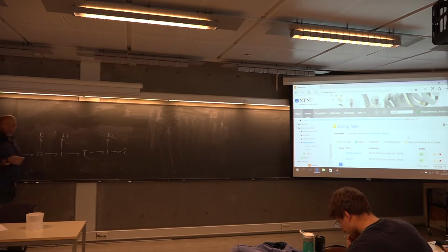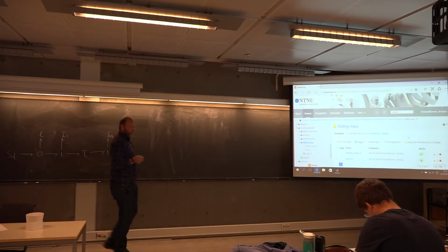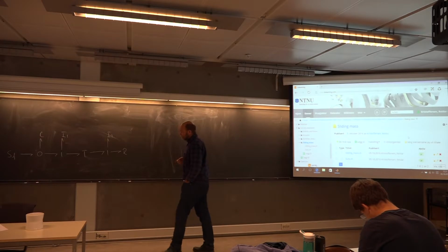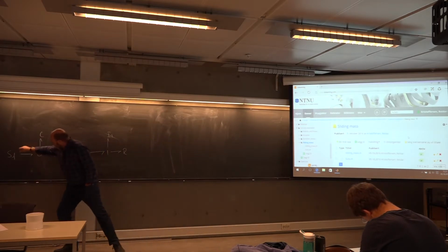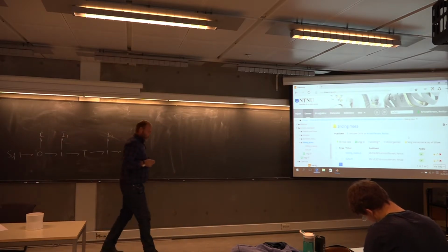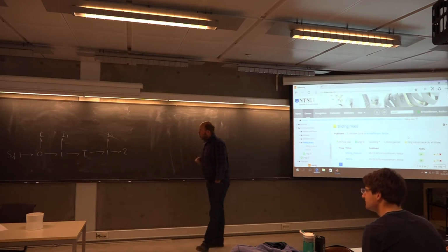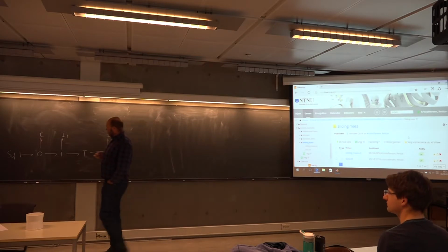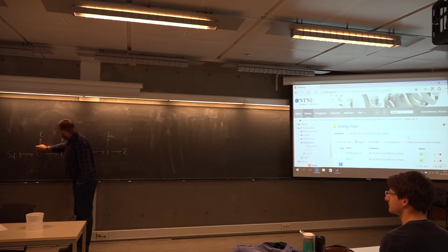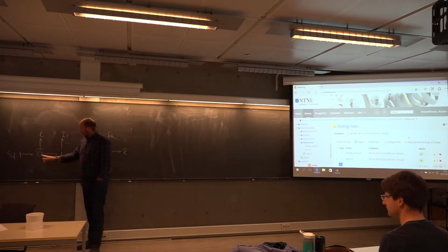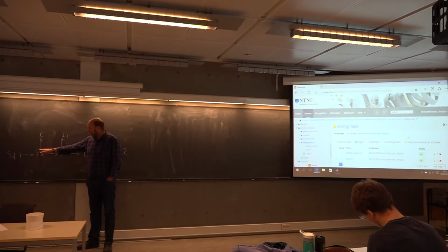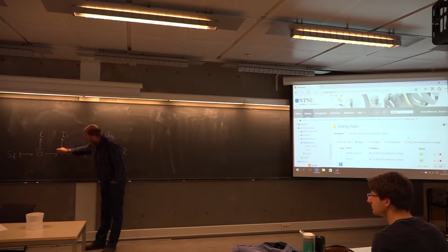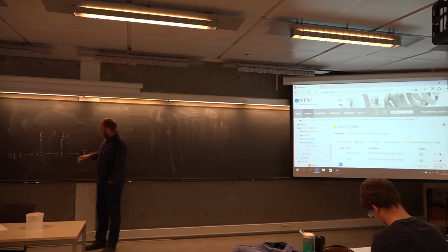Okay, let's try causal strokes for this one. Start with the sources. The flow source has to be like that. That doesn't dictate anything, so we continue. I have a C element here. I choose integral for it. Aha, then this 0 is happy. It has found the 1 stroke towards it. Then the last stroke has to be away from it.